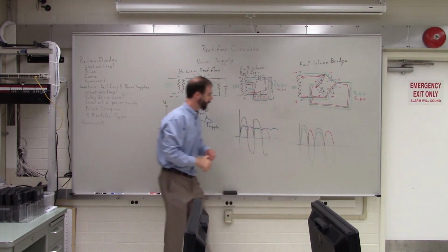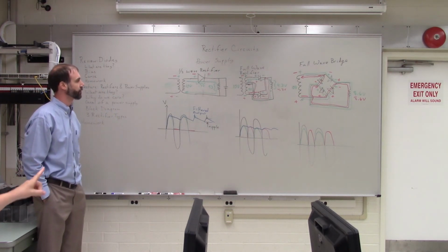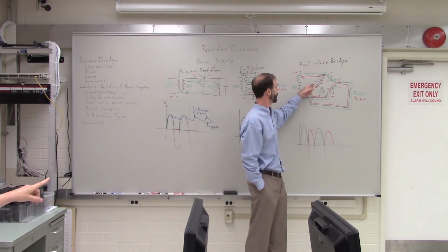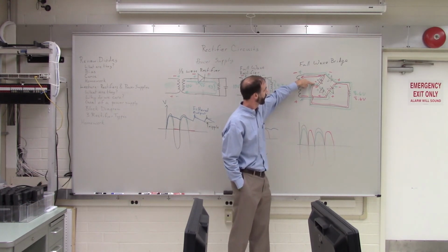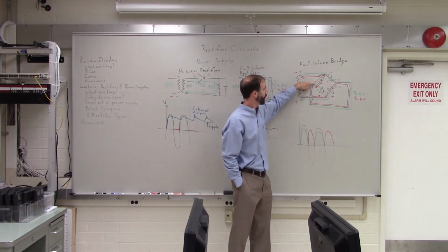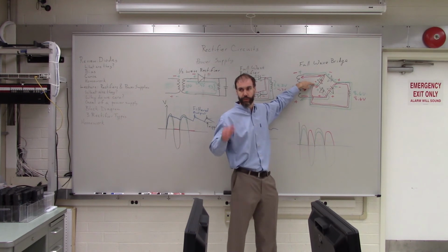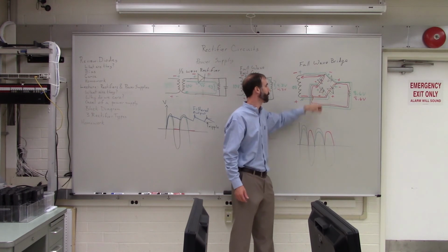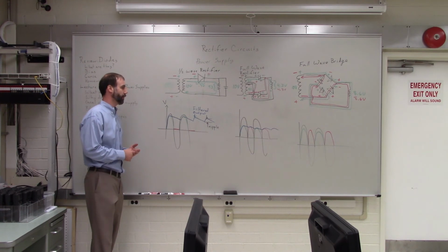Okay. So, I have a question. So at the junction, when it's gone through the load on the positive side, it jumps over, it comes back into the bridge, comes back in right there. Why does it go on the positive side down to that diode and not through the other one? Because they're both positively biased at that point. We're talking about the green line here. Yes, just the green line. Right. So it's already lost some voltage, and it always goes towards lower voltage. Okay, goes towards lower voltage. Yeah. Okay, got it. I see. Okay, that makes sense.